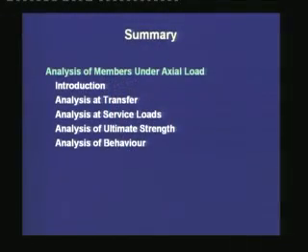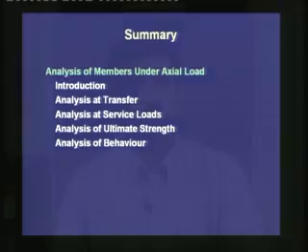Next, we studied the analysis at service loads, where we determined the stresses from elastic analysis using the effective prestressing force after the long term losses and the external characteristic loads. What we should maintain is that the stresses under this effective prestressing force and external loads should be within the allowable stresses under service.